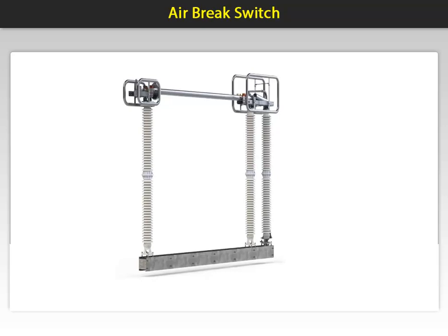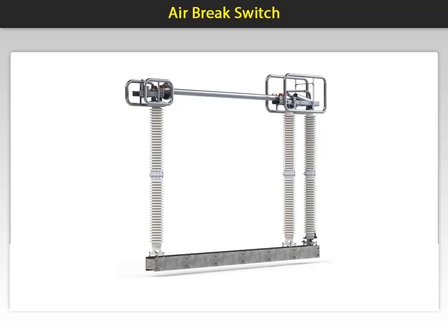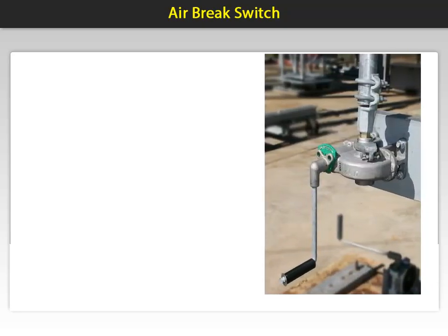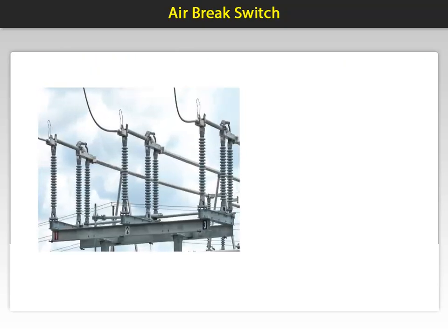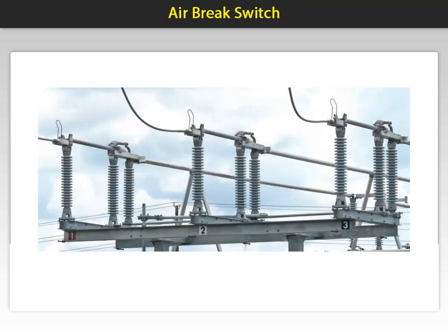It is necessary to isolate the circuit breakers, transformers and other equipment. One option is to use an air break switch manufactured by Southern States seen here. This is a single pole but can be grouped with 2 other units for the required 3 poles. These are non-fused and can be operated with a manual crank seen here or with a motor operator seen here. The 3-pole group operated switch and mechanism is seen here.